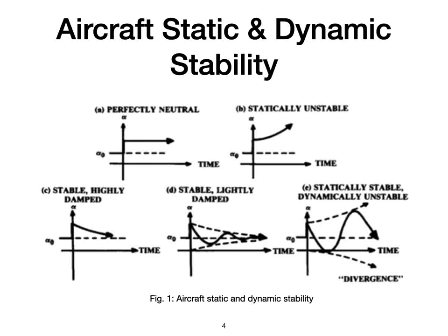Note that dynamic instability is not always unacceptable, provided that it occurs slowly. Most aircraft have at least one dynamic instability mode, the spiral divergence. This divergence mode is so slow that the pilot has plenty of time to make the minor roll correction required to prevent it.